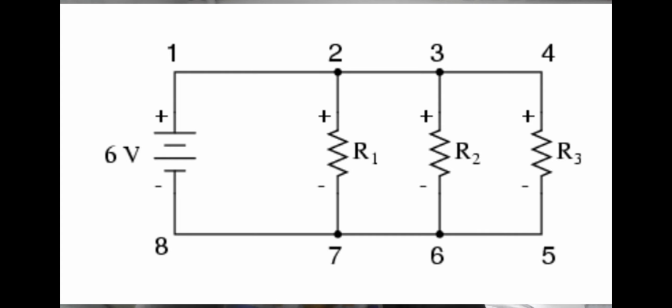And so, because we've verified that Kirchhoff's current law works for both series and parallel circuits, it should follow that it works for series parallel circuits exactly like the voltage law. Although of course, we have to pay attention to combining complicated series into single nodes when appropriate. And just like with voltage, we cannot assume that currents will always add up neatly.